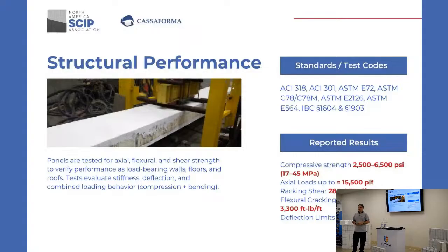Usually for the pouring concrete we will use 3,500 PSI, and for the mortar 4,000 PSI. Those are bags that go for 4,000, even for 6,000.